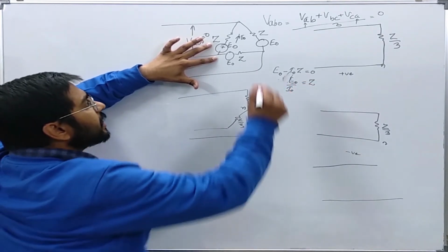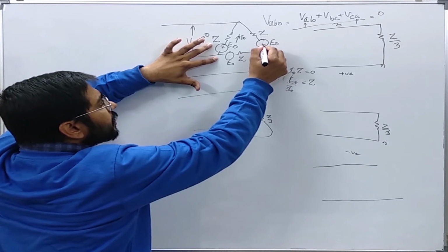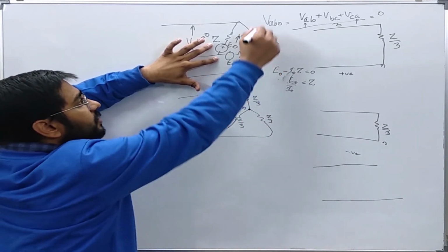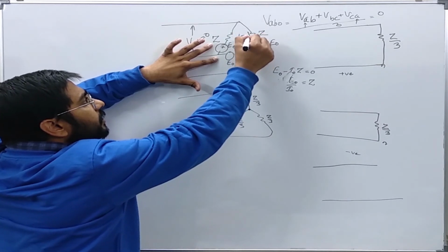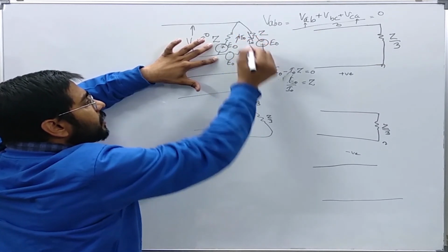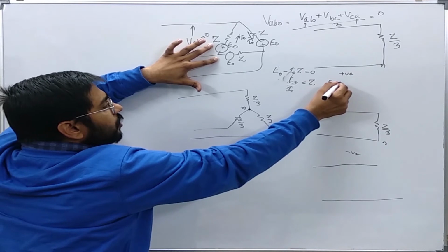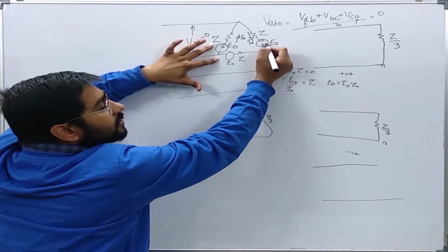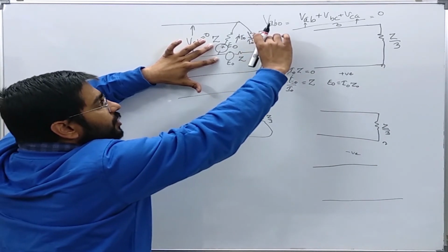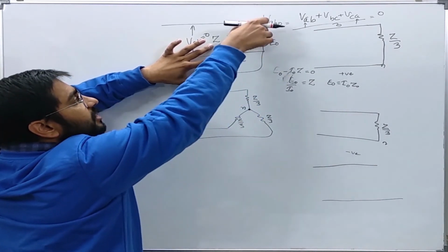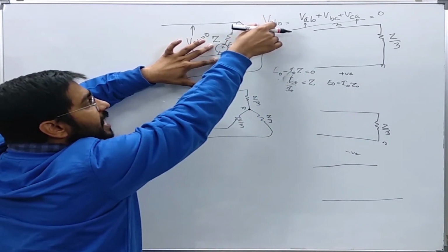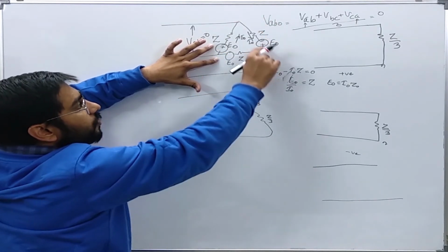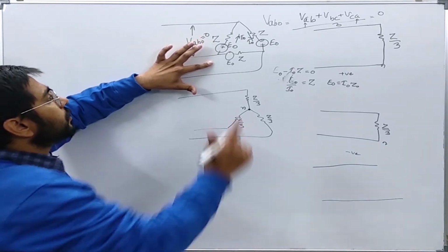Similarly, if this is the voltage source creating some zero sequence voltage, again this current will be I0 such that E0 is equal to I0 Z0. That is, any potential rise in a branch will meet with the same potential drop in the same branch, such that there cannot be any zero sequence voltage drop across the lines.